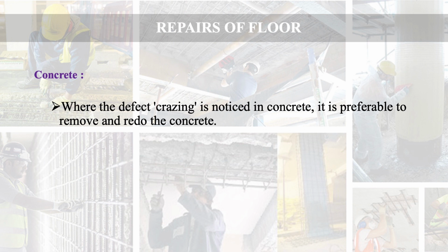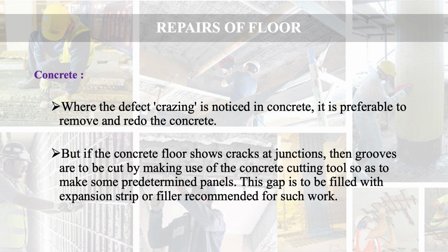Here, if the defect crazing is noticed in concrete, it is preferable to remove and redo the concrete. But if the concrete floor shows cracks at junctions, then grooves are to be cut by making use of concrete cutting tool so as to make some predetermined panels. This gap is to be filled with expansion strip or fillers recommended for such work.